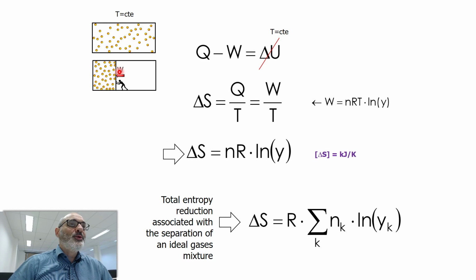So when I compress this gas, its temperature wants to increase. In order to remain constant, it has to reject heat. I'm only talking about internal heat exchange; there's no external heat exchange. And we know the definition of entropy variation, delta S equals Q over T, where T is constant.